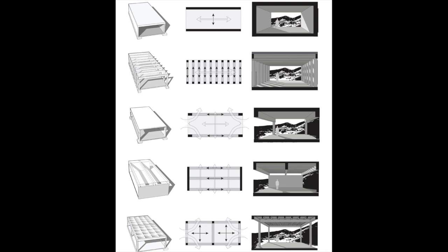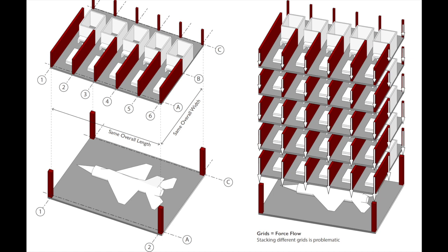But of course, we can help inform what those choices are if we get into a little bit more detail about how these are assembled. One way is thinking about the relationship between the structural typology that you use and the functional qualities of the space that happen. In the top over here, you see a small apartment building. In this apartment building, I know it's a small module. Maybe I'm using the red CLT walls to 1) define the module and 2) be the structure. So I can have grid lines 1 through 6, A, B, and C. And all that works fine for that particular function.